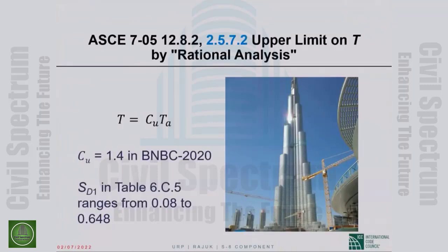Now, a rationally computed period. You can calculate period by any rational procedure as long as it is in keeping with the principles of mechanics. All of that is true. But rational period computation depends on your stiffness assumptions. If it is a concrete building or a masonry building in particular, by taking cracked rather than gross stiffness,